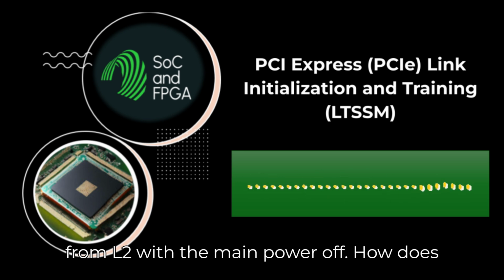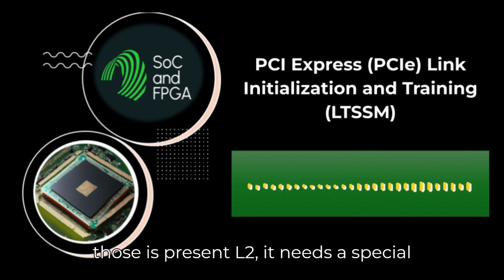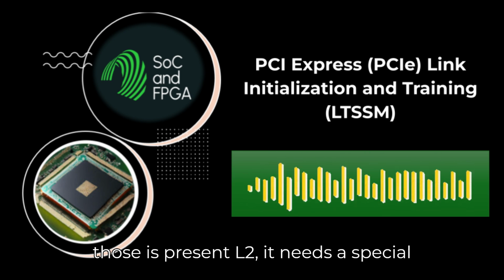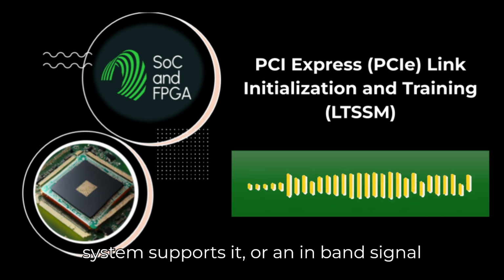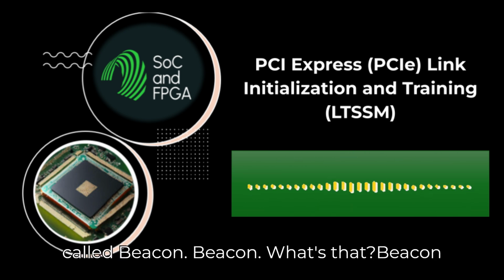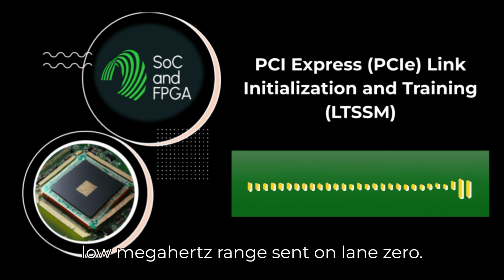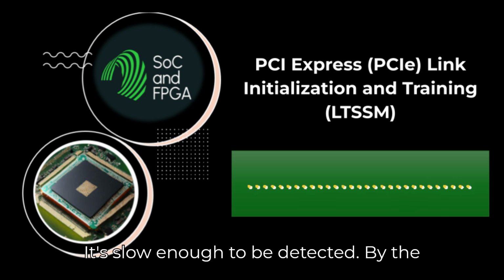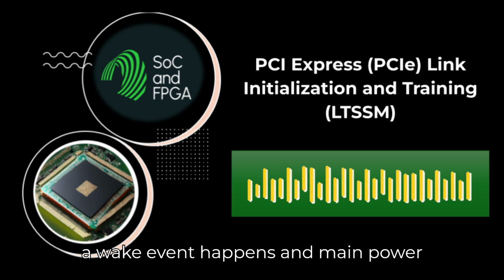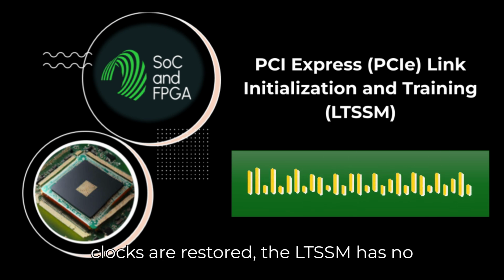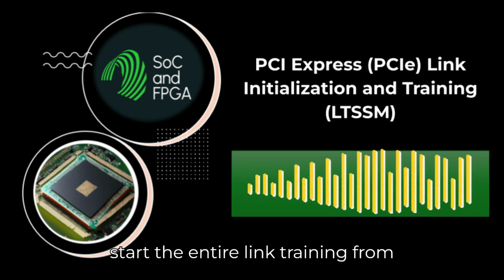And waking up from L2, with the main power off, how does it even get a signal? Good question. If Vaux is present, in L2 it needs a special wake-up event, either a dedicated sideband signal called WAKE#, if the system supports it, or an in-band signal called beacon. Beacon, what's that? Beacon is a very low-frequency signal, kilohertz or low megahertz range, sent on lane 0. It's slow enough to be detected by the minimal circuitry kept alive by Vaux. Once a wake event happens and main power and clocks are restored, the LTSSM has no choice but to go right back to detect and start the entire link training from scratch.